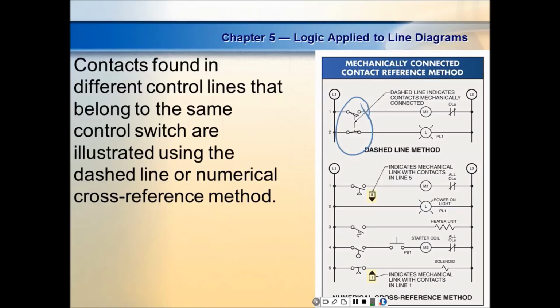Look at, not line 5. Line 5. You're going to have to get out of that habit, even though it does work out the same. In motor controls, rungs do not have numbers. When you take PLC, the rungs are numbered. So you start a new rung, and all the rungs are numbered. In motor control, rungs are not numbered. What's numbered?